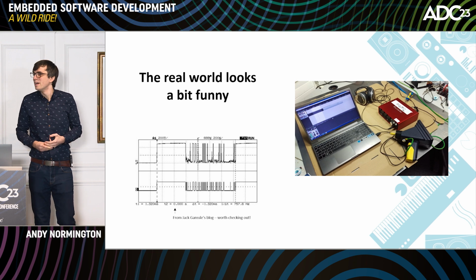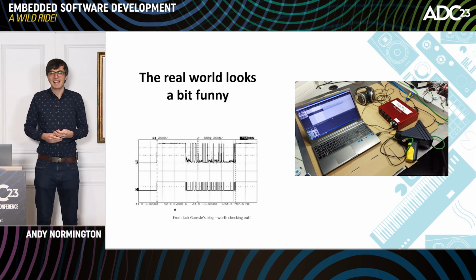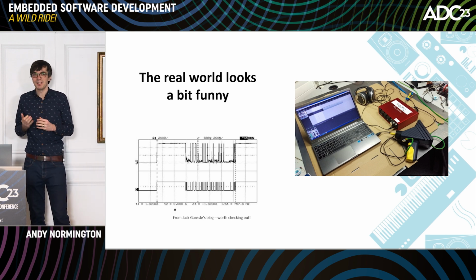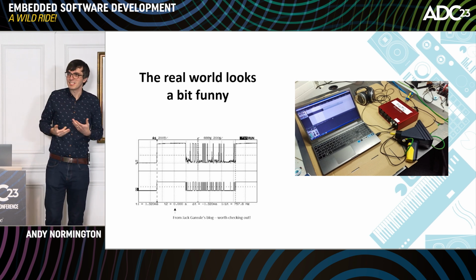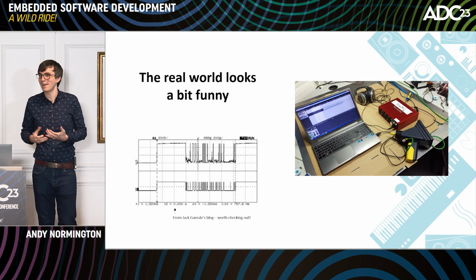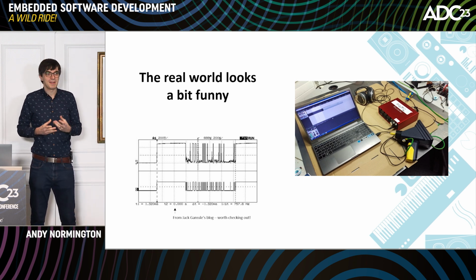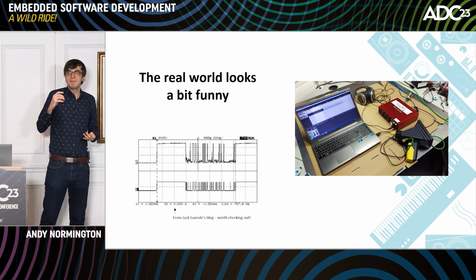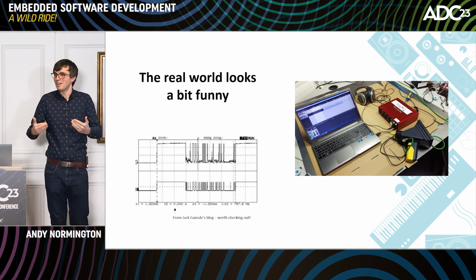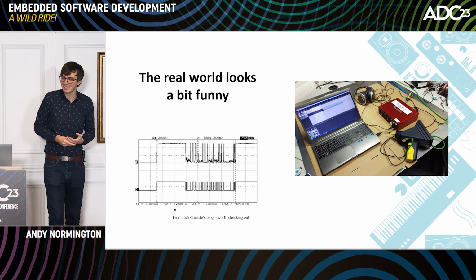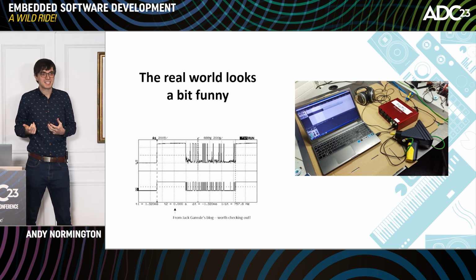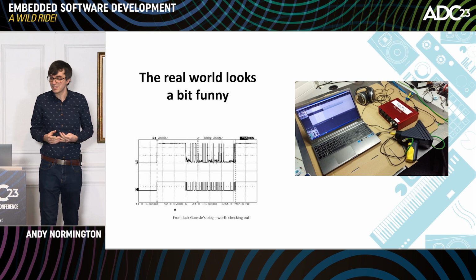but I bring it up because there's firmware tools that we could use as well. Pretty much every microcontroller has a dedicated watchdog peripheral. This is a timer that we can reset when things are going well and stop that timer timing out. If that timer ever times out, then we know something's gone wrong and we can set what happens with that timer. Maybe it just resets the whole system and we start afresh, hopefully without the voltage spike this time. Or maybe if it's a bit more sophisticated, we can kill a thread in the OS and restart just that bit.